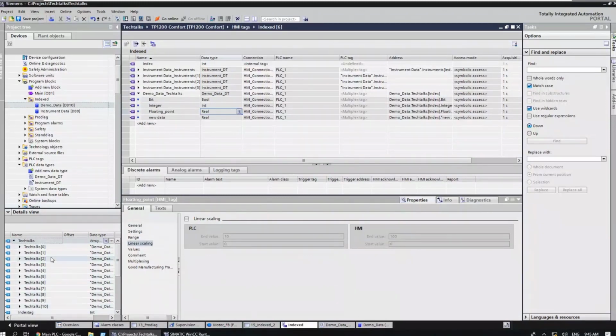So if you do a 0 to 10 but only put a number in of 1 to 10, it just makes it easier to understand. It's just a little tip that helps you avoid confusion. So always number your arrays inside your PLC as 0 to however many items you want. So by changing that array index now, we can move through.